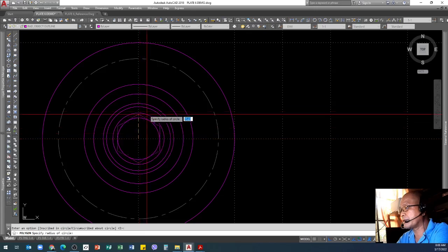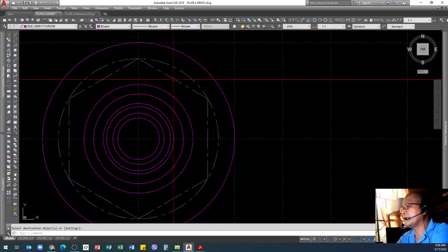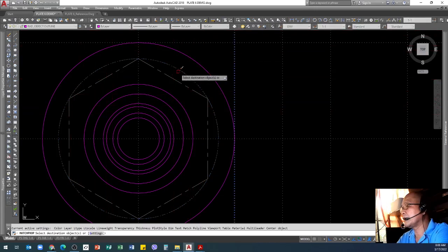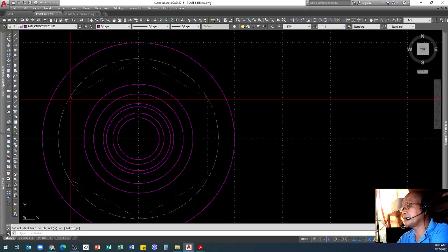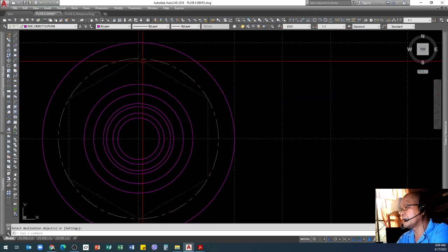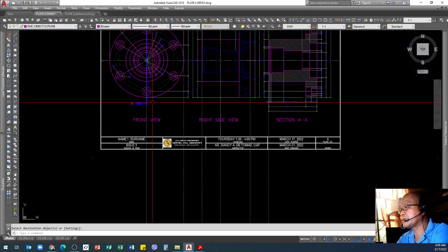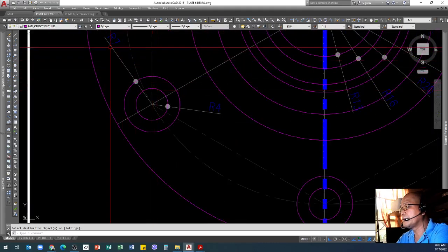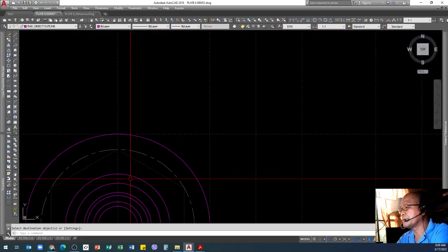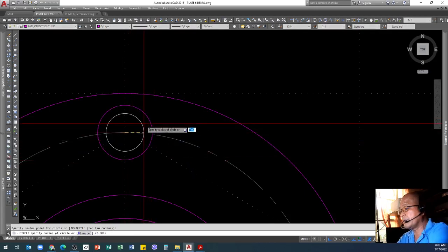We will use inscribe, and then locate this one. Okay, and then change that color to be a guide also, or we can use the guideline only. Yeah, because that's for the location of the circles. So now we are ready to draw the small circles there, two circles, which have a dimension of 7 and 4. So circle, then diameter is 7, and then another one is 4.